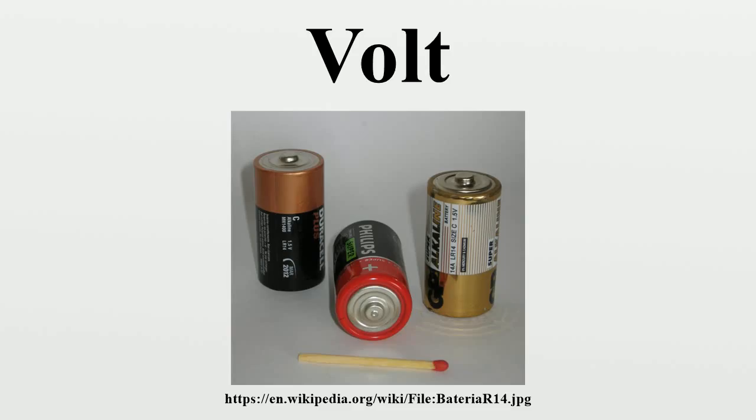In alternating current, the voltages increase, decrease and change direction at regular intervals. As a result, voltage for alternating current almost never refers to the voltage at a particular instant, but instead is the root mean square voltage, which is a way of defining an effective voltage when calculating power. In most cases, the fact that a voltage is an RMS voltage is not explicitly stated, but assumed.